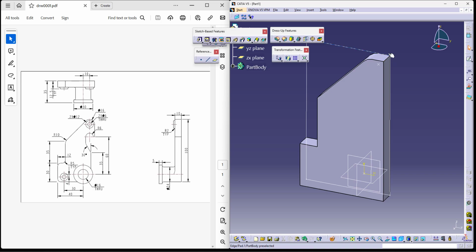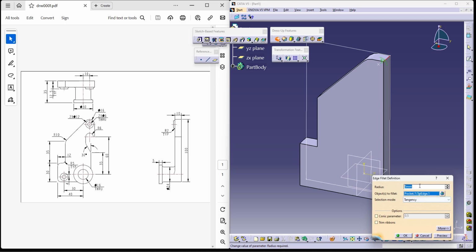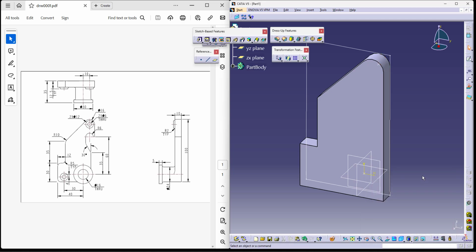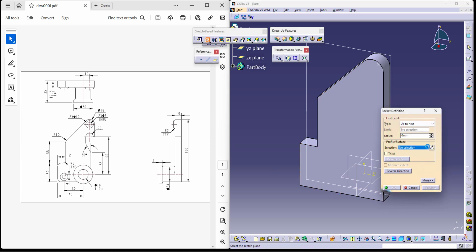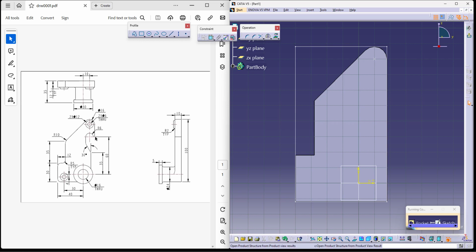Now on this side, you can either give a round or you can create an arc cut. I would prefer giving a round of course 8, because it has 16 dia. Now we can proceed a little more further in making our cuts. Now again I'm using a pocket. The second cut, what I'm trying to make, is maintaining the dimension is this one.